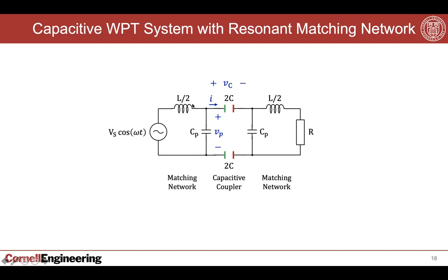And to see how this increases your voltage, think in terms of this being like a parallel resonant converter, where you essentially have an L and C which resonate now in parallel instead of in series. And if you were to plot the voltage Vp, which appears across the capacitor, at the appropriate frequency where L2 and Cp start to resonate with one another, you will get a large boost in voltage.